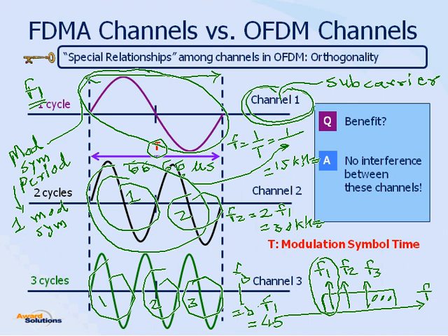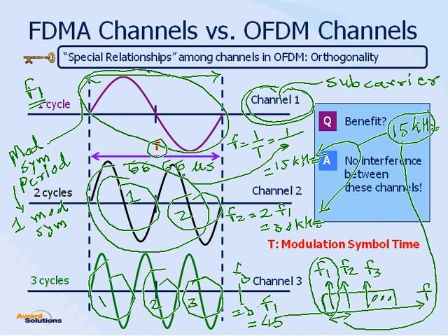Now, if you observe, the difference between adjacent subcarriers is exactly 15 kilohertz. So that is the subcarrier spacing. Between 2 subcarriers, the spacing in LTE is always 15 kilohertz, fixed in the standard. For a regular cell that is supporting several UEs, email, web browsing, those kinds of applications, that kind of a cell will use the subcarrier spacing of 15 kilohertz. Same way between F2 and F3, 30 kilohertz and 45 kilohertz, the difference is again 15 kilohertz.